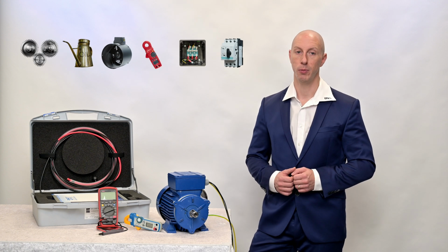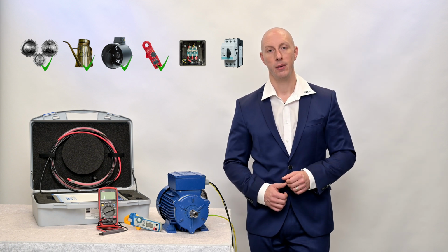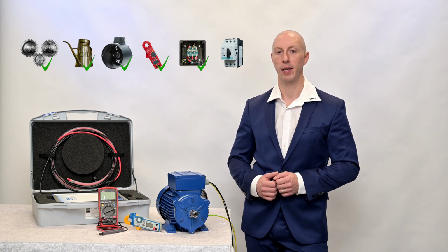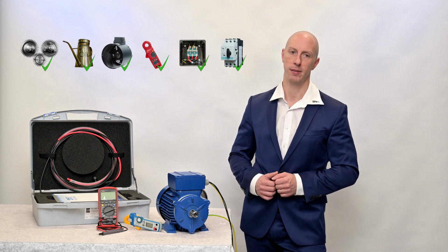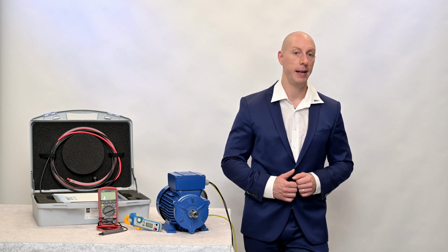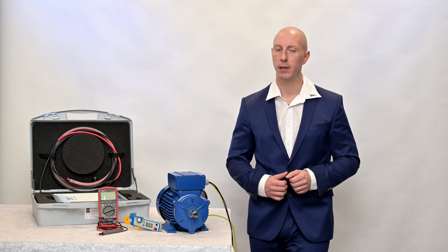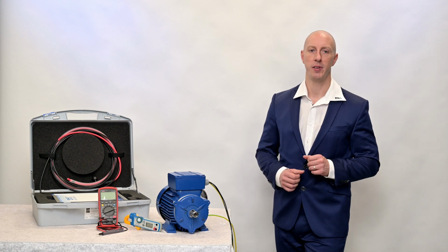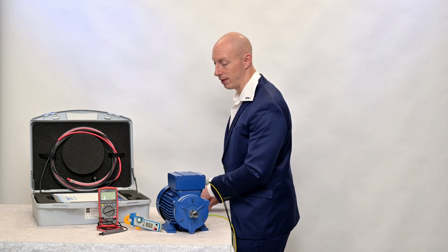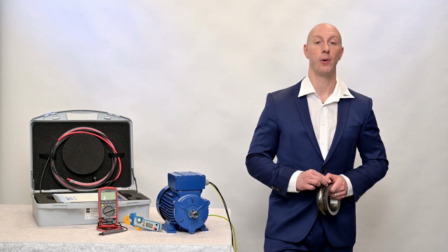Mechanical stresses are checked, lubricants, cooling, current consumption, and the correct electrical connection are scrutinized, and all protective devices are tested for their effectiveness. If no fault is found after all these measures, the question of how to proceed is not easy to answer. The first question you should ask yourself is: is the motor operated via a frequency inverter? If so, you've come to the right place in this video.